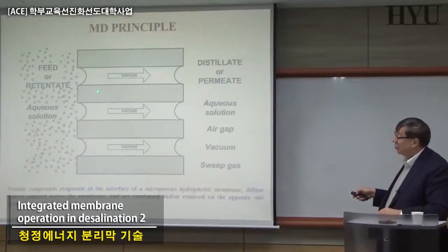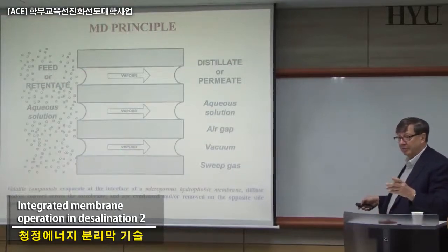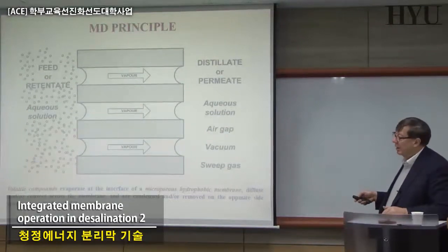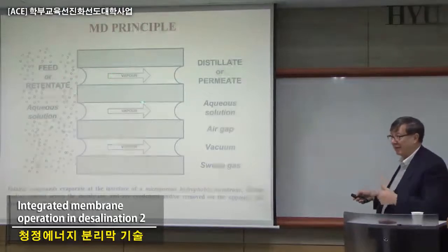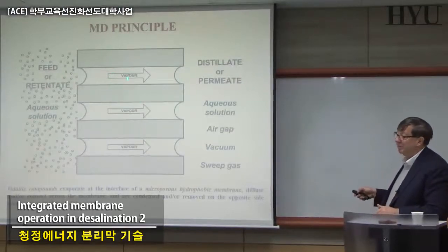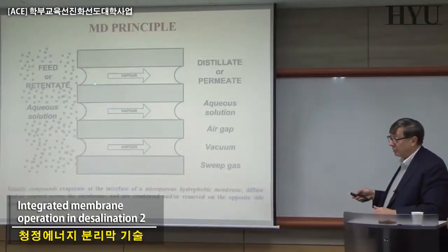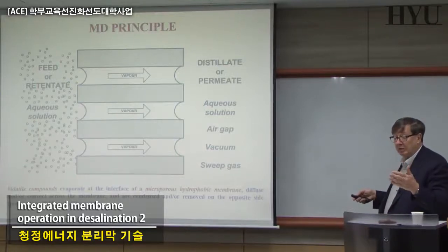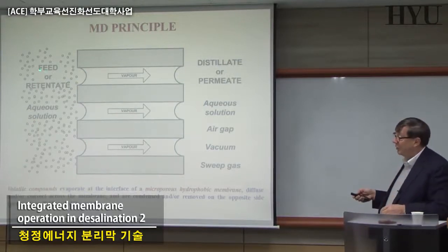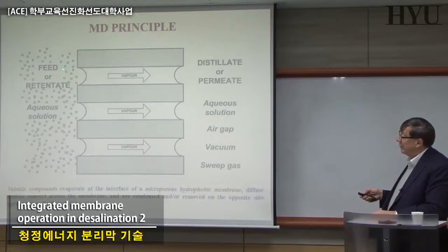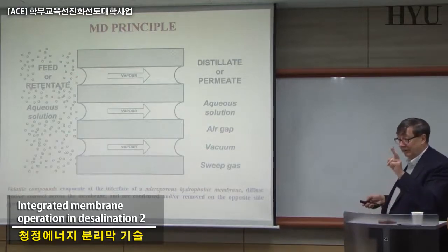But there are a lot of pores, billions of pores, with the right appropriate size, for example, 0.2 microns. At the interface between the liquid phase and the gas phase, that means the vapor, assume that it is empty initially, you have just the gas initially, you will have at the pore interface evaporation, as always happens. Some molecules from the liquid phase will go into the vapor phase, with the Clausius-Clapeyron equation, etc. And that means if you apply here a small delta T, the temperature has two effects.